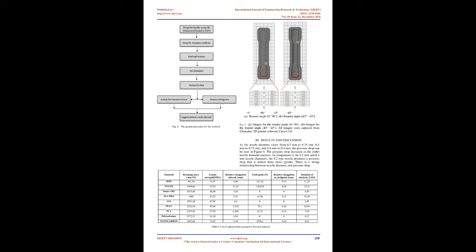15. Using two combinations of raster angles, 45/-45 and 0/90, along with three different infill speeds, parts were fabricated in 3 dimensions. Two types of 3D printing materials were used in this study, polylactic acid, PLA, and tough PLA.